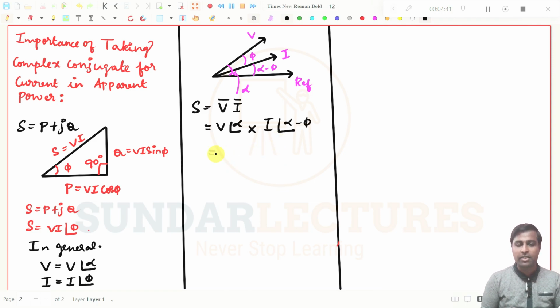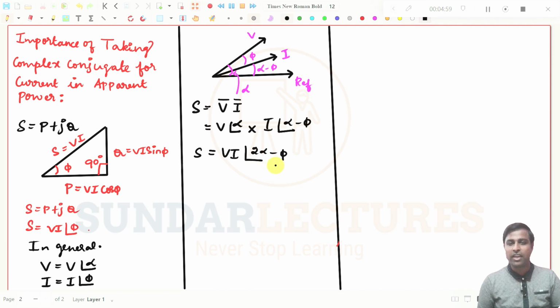And if you multiply these two, what will you get? Obviously, this is V into I at an angle of, you have to add these two angles. If you add these two, alpha plus alpha, it will be 2 alpha minus pi. See what we are getting here: S, which is equal to VI at an angle of 2 alpha minus pi. We know that S should be VI at an angle of pi, it should not be 2 alpha minus pi. It is a wrong answer, right? You are getting some other angle value here.